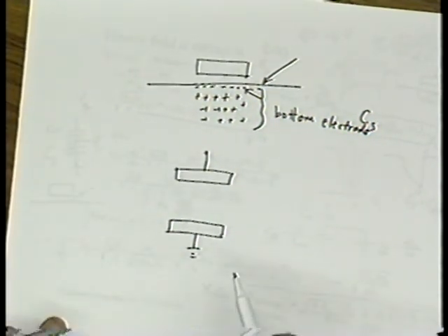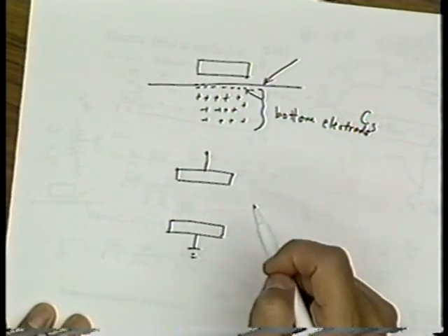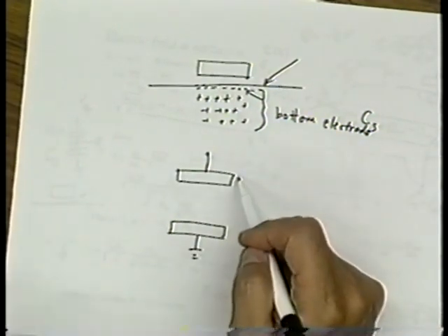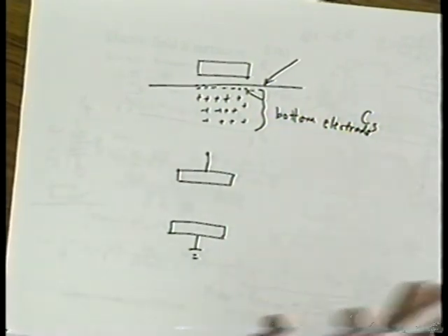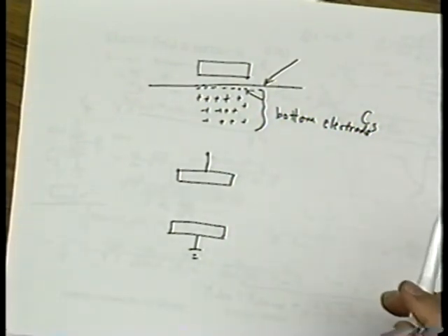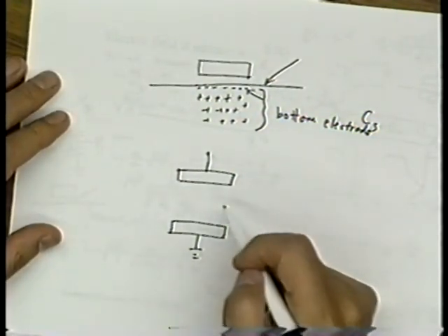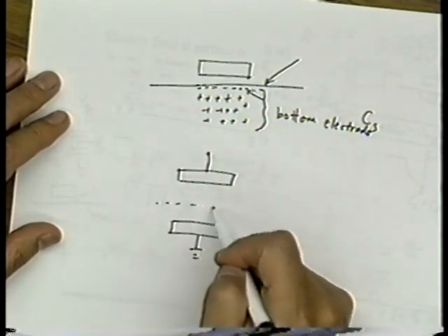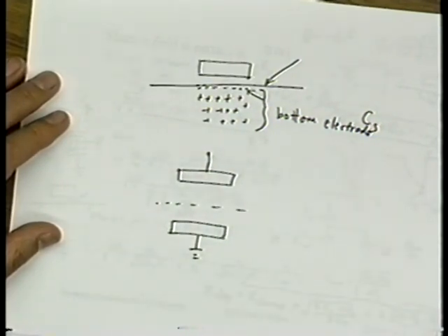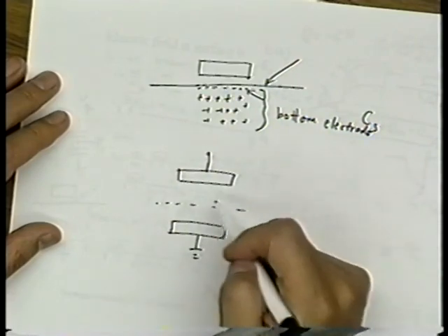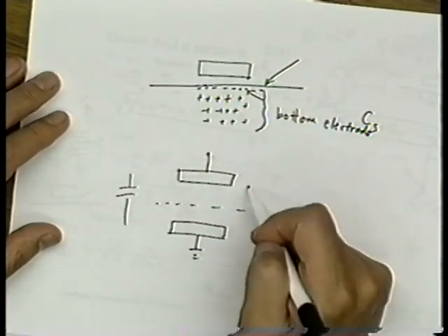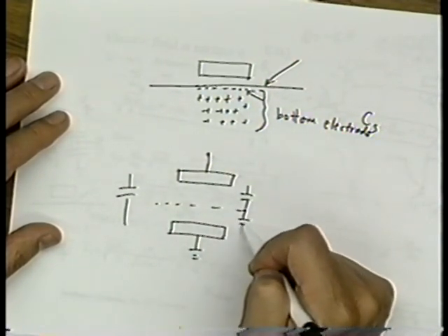Go back to the standard parallel plate capacitor. These are two metal electrodes, not MOS. Everything's simple, right? I think you all agree with me that we can arbitrarily break the dielectric into two, and reinterpret this one single capacitor as two in series. There's absolutely no problem.